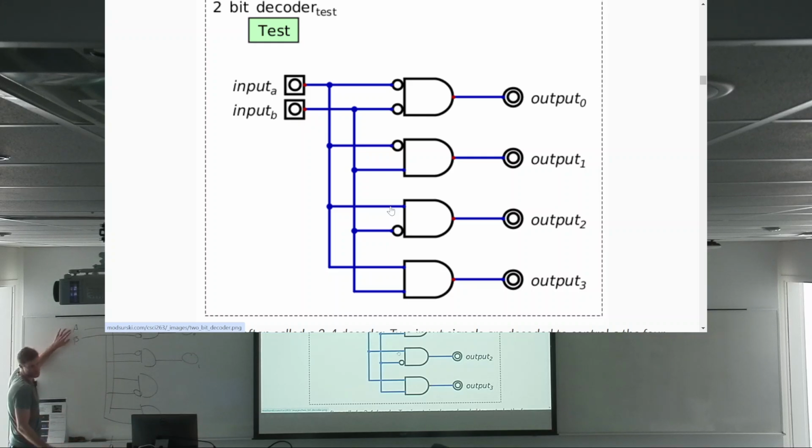We've got these 2 signals. Now I can be up in my bedroom looking out the window at my beautiful flower beds, and I want to water that one, so they're both in this state. Then I change the state, then I change the state, then I change the state. And I can control 4 circuits with my 2 lines. This is what we call a decoder.